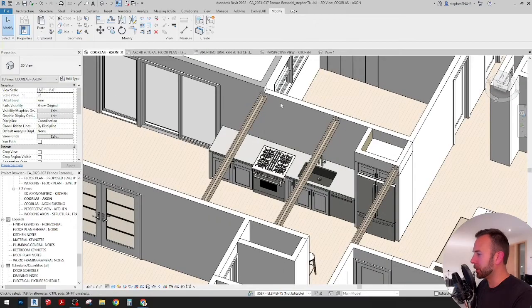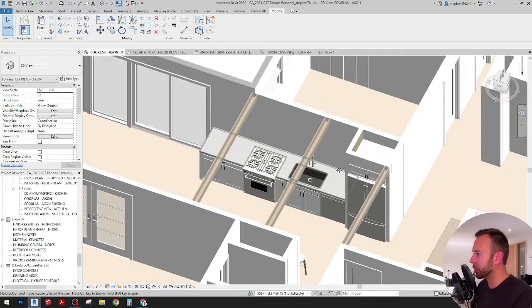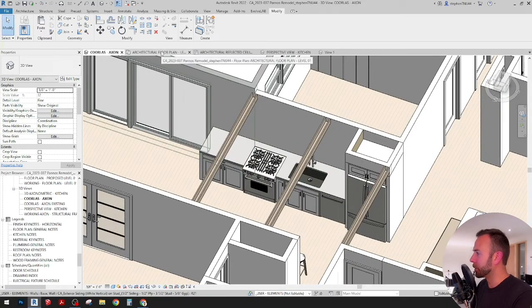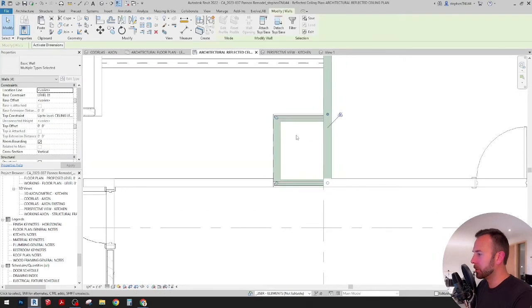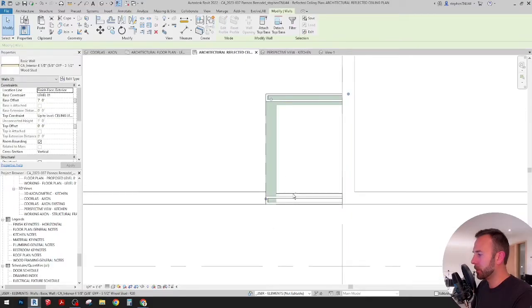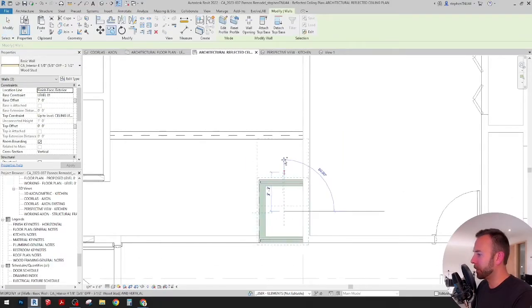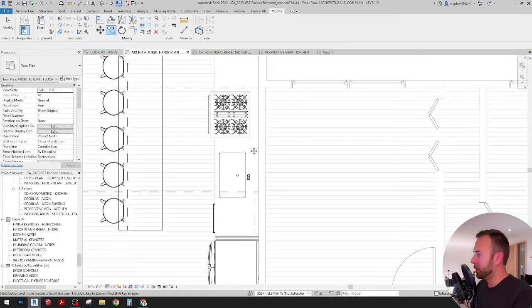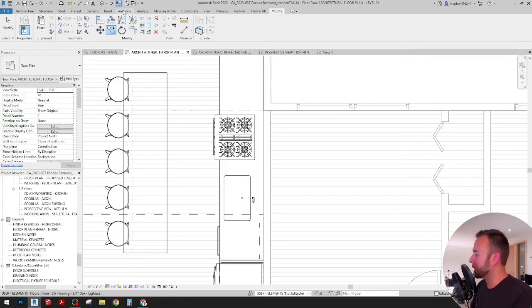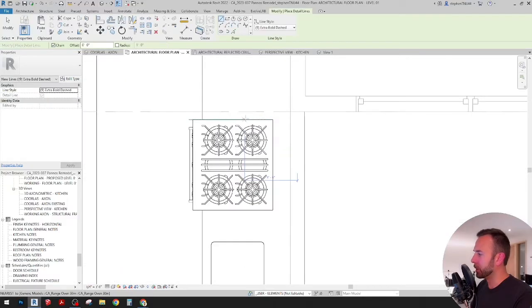And now let's look at the hood. We'll put in our hood insert and then see what kind of wall space we have left over for cabinetry. So I'm going to go back into my reflected ceiling plan, take these walls, and copy them down. I don't know exactly where it is, so we'll have to go back in our plan. And when translating things to plan, in Revit, in the reflected ceiling plan, you can select the underlay to be the floor plan. That's a fine option.